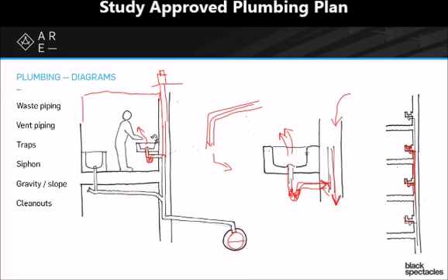So we have the idea of a plumbing fixture, say a sink or a water closet or a shower. Each one of those is going to have a drain pipe. That drain pipe is going to have a trap that traps the wastewater in it, so that that wastewater can become a trap for the sewer gases. Each one of them will then connect to a larger system that eventually gets out to the sewer in the street. And each one will also have a vertical vent pipe that goes upwards towards the roof or some outdoor outlet.